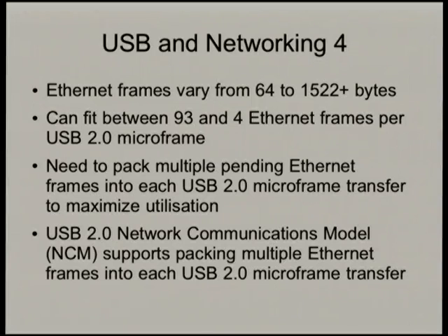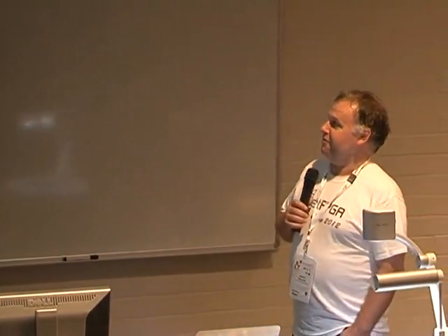And therefore, to make best use of your USB space or your microframe time, you want to pack multiple Ethernet frames, if possible, into each USB 2 microframe. So if you're only sending one Ethernet frame during each USB 2 microframe, you're not utilising your USB to the max.